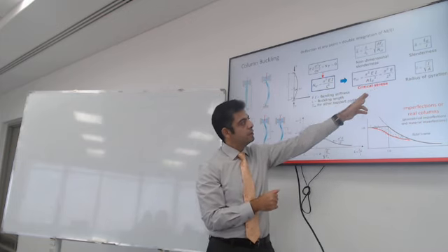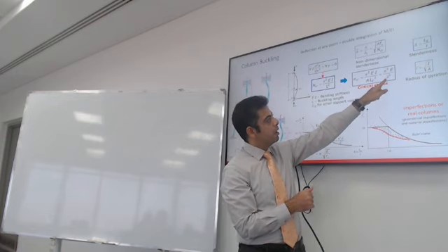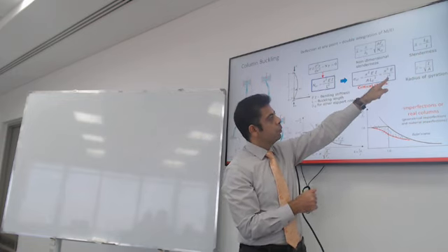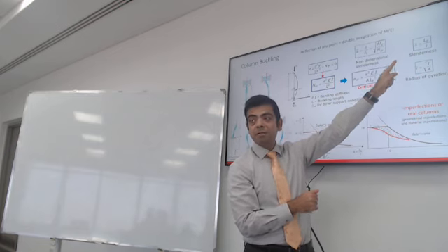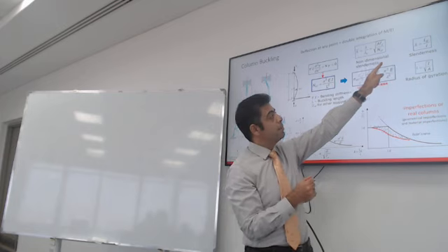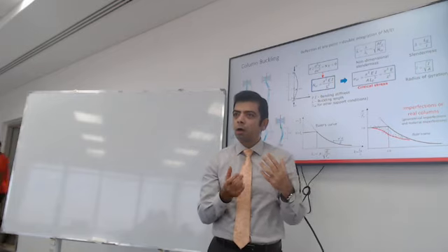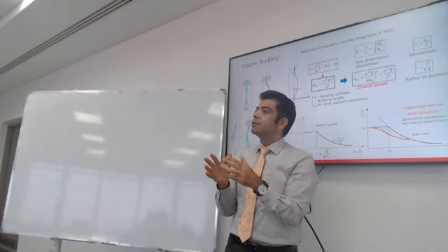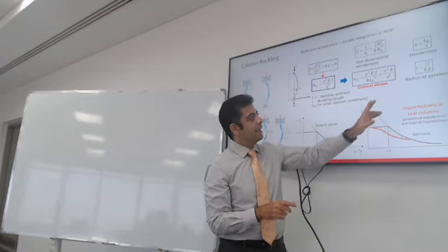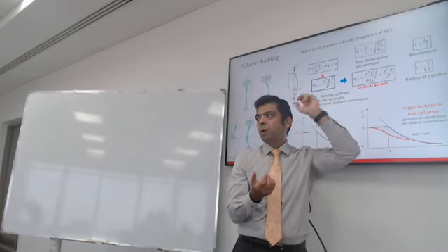From this expression, you realize that it's very beneficial to use the slenderness ratio lambda. Slenderness ratio lambda depends on the effective length divided by i or r. Some codes will say it's i, some will say it's r. It's the radius of gyration. What it is, it's the moment of inertia of the cross section divided by the area under the square root.